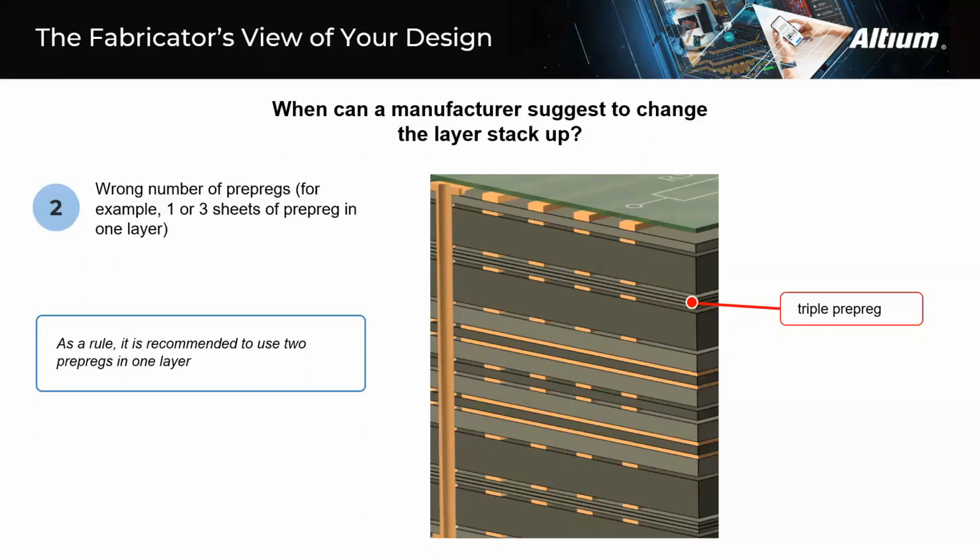In this situation, you will be offered an opportunity to adjust the layer stack-up, choosing from the existing range of materials that provide the parameters you need. Designers want to be sure to study the requirements for the layer stack-up and, if possible, use known good layer stacks either from within your organization or from your bare board fabricator.